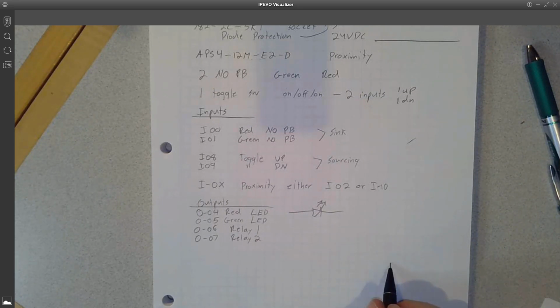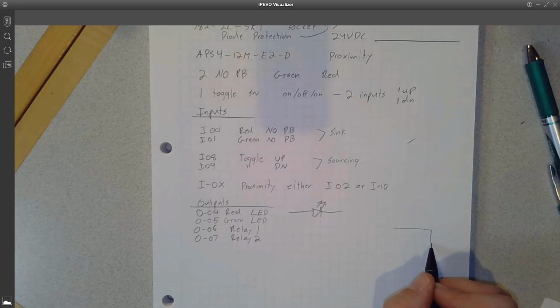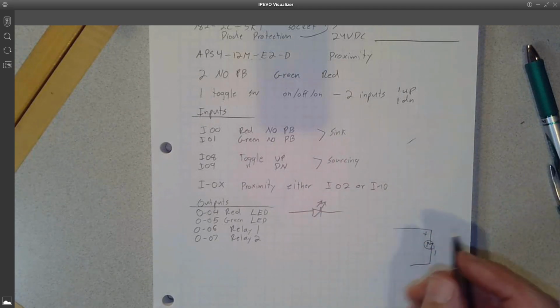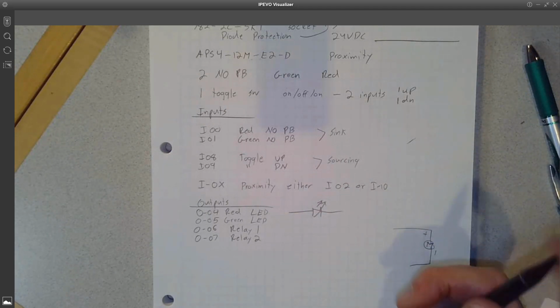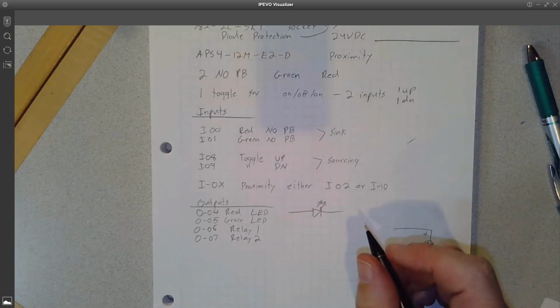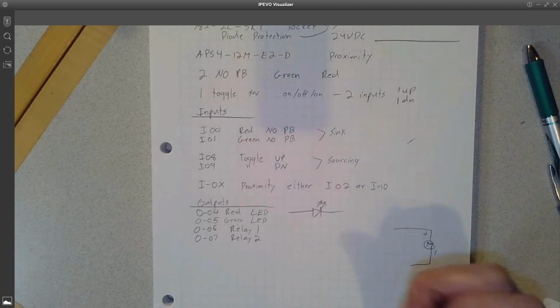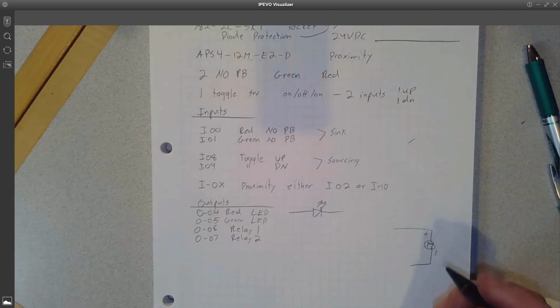So it ends up feeding a motor with positive, negative, or vice versa, depending on how the relays are turned off and on. So this is one of those examples where I'm telling you there's lots of resources out there on how to do it. I just start searching on Google, reversing DC motor with a relay. There's 2 most common varieties of how to do that.